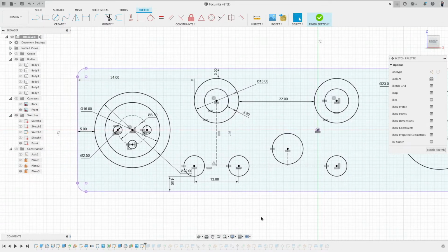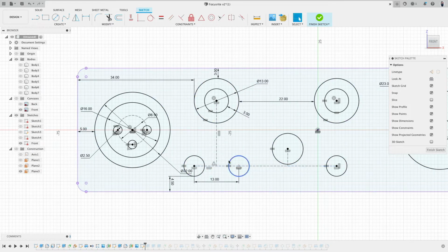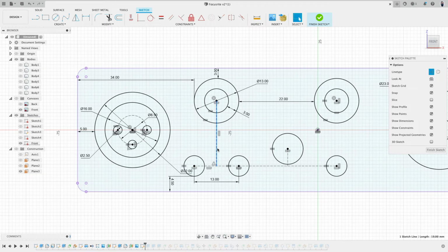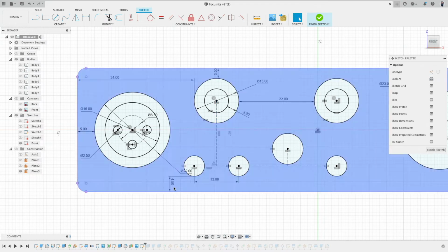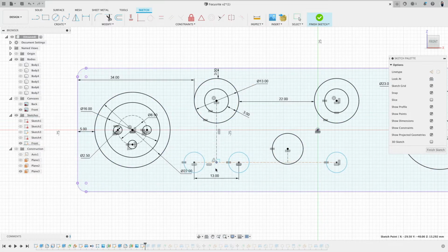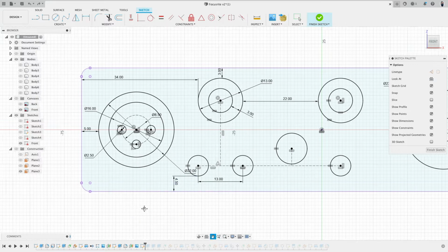So all these constraints are just geometrical rules we established. And then here, these 2 rings, we drew a line and a line. The line is horizontal, line is horizontal. And then to make them left and right centered to here, just a vertical line. And that line is centered. There's no distance for this line because that's actually given by this. So we have here the right click arc tangent dimension of 4 millimeters. Okay.